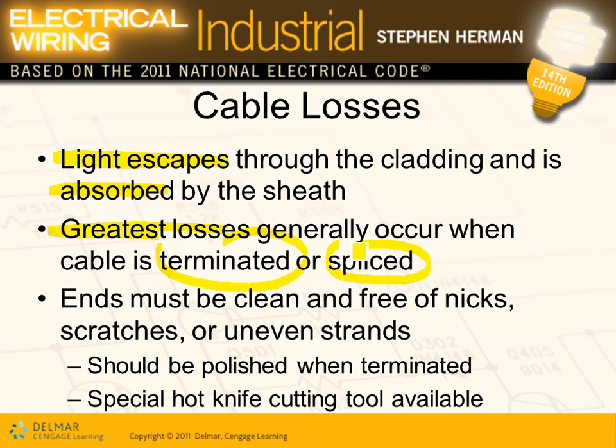So when you do the splicing, gentlemen, you need to clean and be free of nicks, scratches, and uneven strands. So they have a kit, Adam, that they give to whoever installs the fiber optics, Karen. They use a special kit to terminate, cut and splice the fiber optics, with very special cutting tools to make sure the termination is proper so they don't lose more data than we need to. Then you do polishing at the termination. Special hot knife cutting tool available.